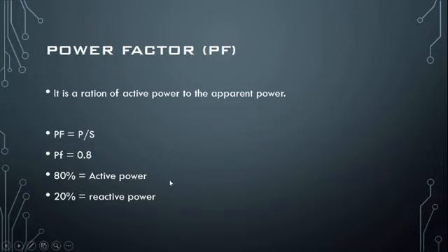So that is why the power factor is important. Now to sum up, the power factor of a circuit or device is simply a way of stating what fraction of its apparent power is real or active.